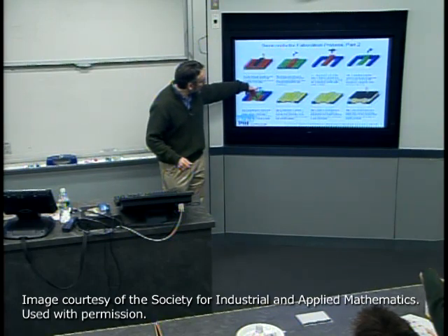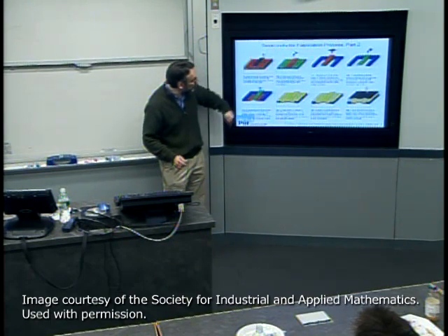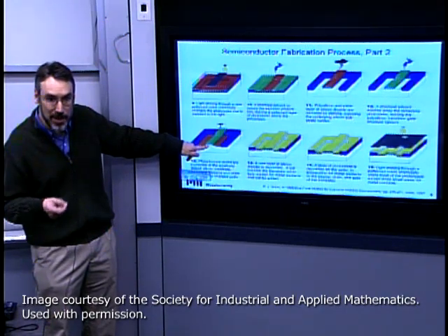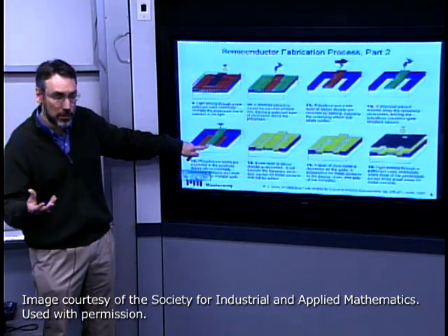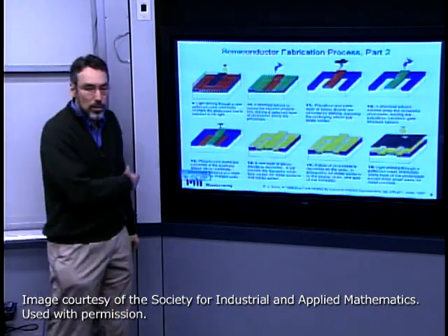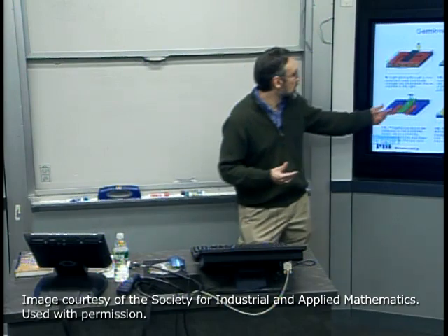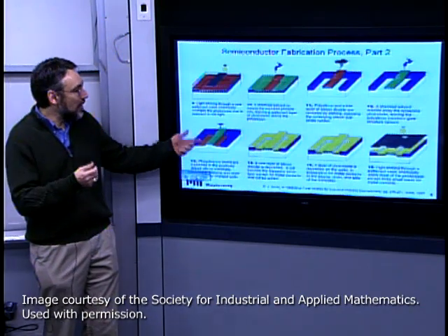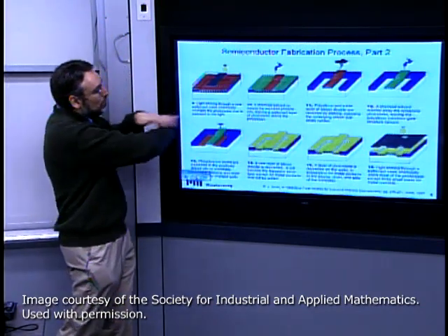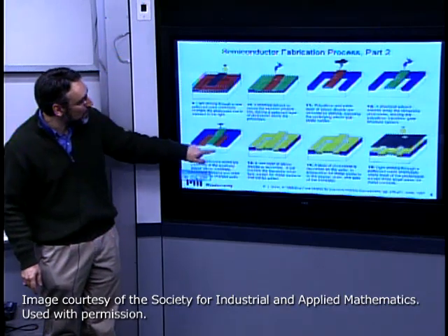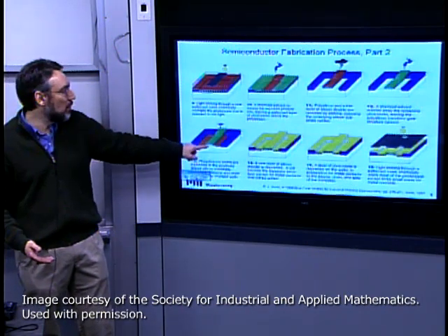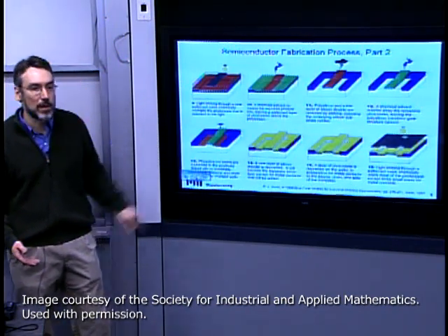The basic idea there, again, is we're highly doping in a controllable fashion just these regions. Those regions we don't want to dope underneath the channel. We want to keep that fairly lightly doped so that we can invert it for electrical action. And in this case, we're getting something often referred to as a self-aligned process whereby we don't have to selectively shoot the ions just in here. We can blanket the whole wafer and use the thick oxide and the polysilicon as the mask itself to prevent the ions from reaching the underlying silicon regions.